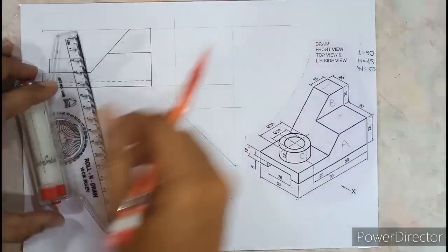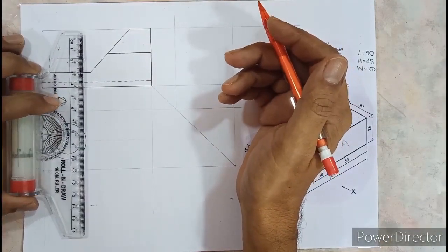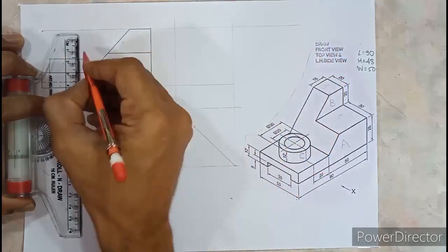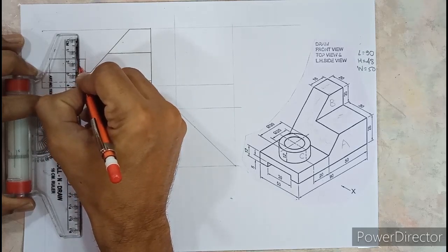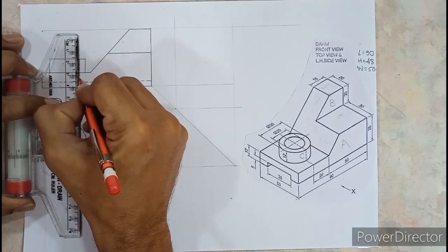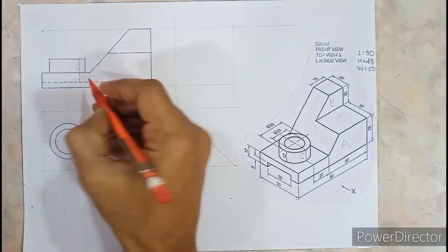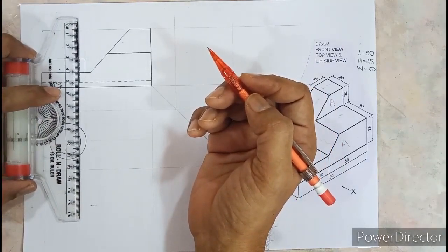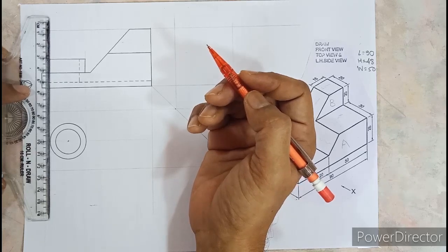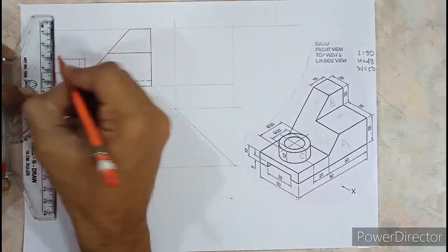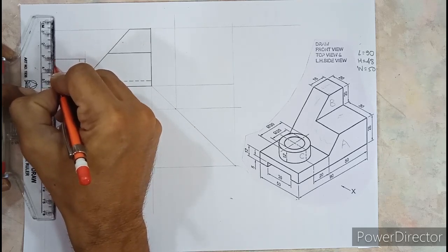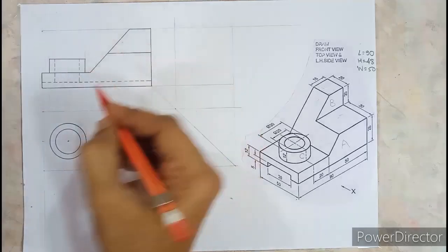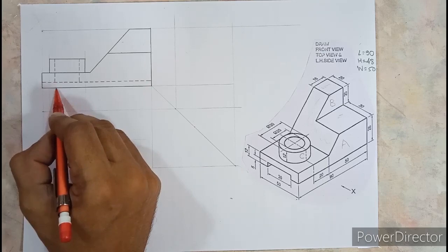So here when you draw the cavity depth, I'll align the scale like this. Okay, let me slide behind. And from here you need to draw a hidden line such that it should intersect another hidden line. See, like this till here. Same way here also. So from here, if I draw a hidden line, the depth of the hidden line should be such that it should meet another cavity. Cavity cannot extend beyond this because there is no material.